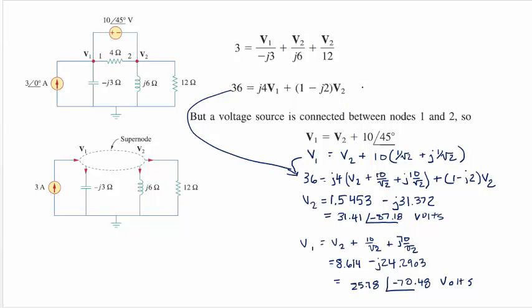Fixing that up a little bit, you get this math. So we have a V1 and a V2, and we need a constraint equation. What we recognize here is that V1, this voltage right here, equals this voltage here, V2, plus this 10 volts at a phase angle. So that's what we write right here. I clipped some of these out of your textbook because the V's are bold to remind us that they're really vector-like quantities.